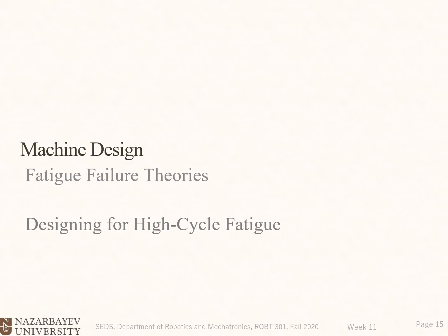I could say that so far you understood the fundamentals: how to find the S-N diagram, how to find fatigue strength, or Sf. So we managed to find the fatigue strength based on the S-N diagram, and now you know how to calculate the fatigue stress concentration factor. But so far we haven't developed any theories.